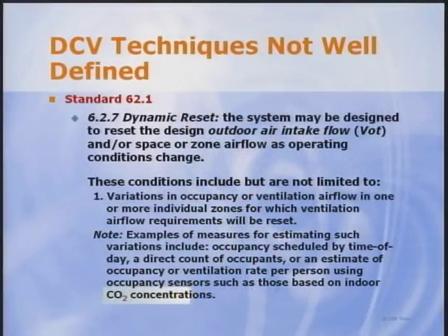These two measures could not allow a partial reduction in ventilation rate because only the presence of people is known, not the number of people. To partially reduce outdoor air rates during occupied periods, either a people counting device must be used, although certainly that's not a common approach, or CO2 concentration must be used. I'm going to focus on CO2-based demand control ventilation since it is the most common approach.